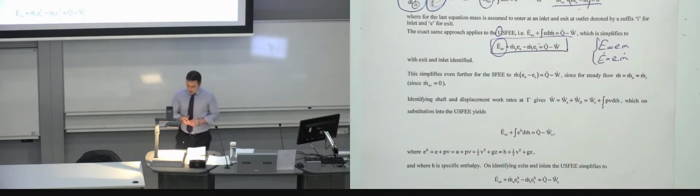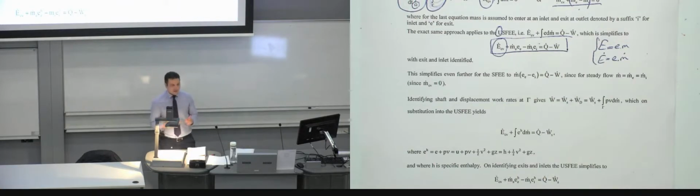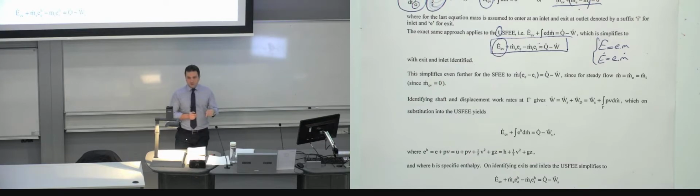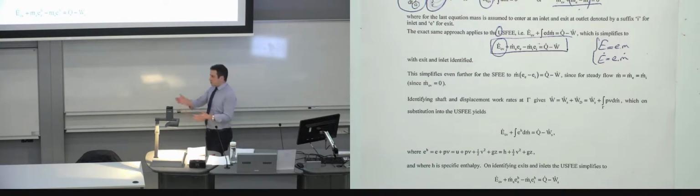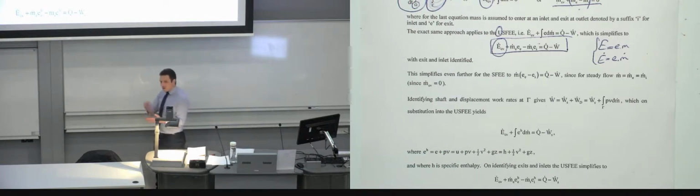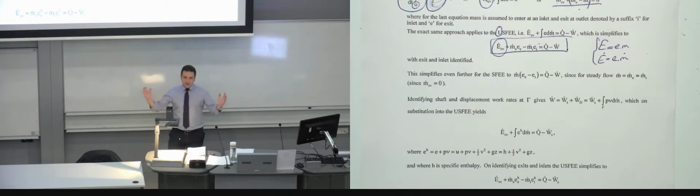This is the part where we are going to introduce, or actually again remind ourselves about the work. So far we've seen two different forms of work. One was displacement, the other one was shaft work. Remember? W_S, subscript S, that's shaft work. For example, where you have a propeller or turbine or whatever, a fan in the system. And we had W_D, which was a displacement work as well, which is if you're moving a piston within a cylinder, that is displacement.